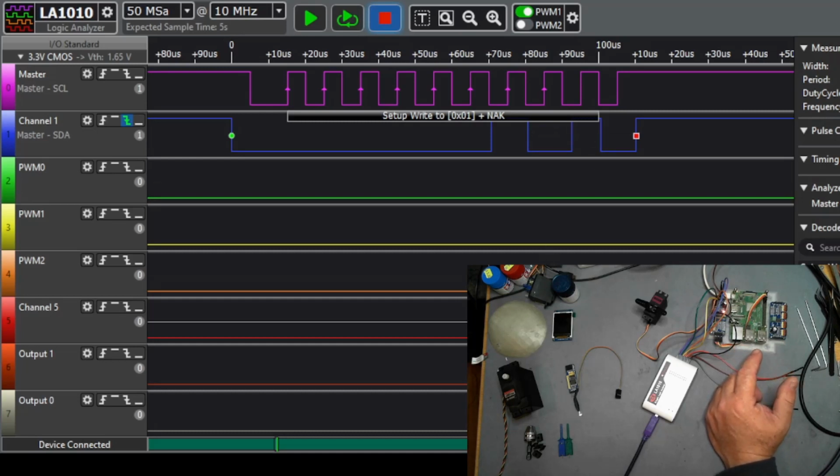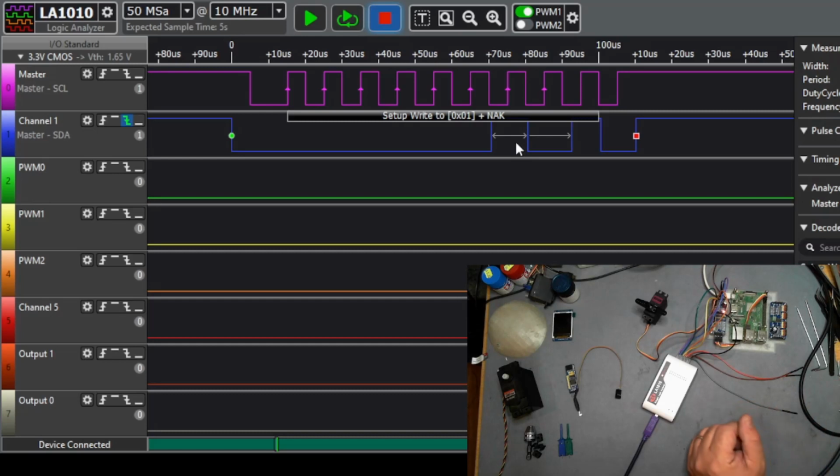So when the Raspberry Pi, MyRobotLab, does an I2C bus scan, which I've just done, it's actually just looking for an acknowledgement from the address, and it will actually send a read and a write to each individual address, all 124 or 126 addresses, looking for a response. Whenever a device responds, it just holds that acknowledge line down for that clock cycle. Alright, so let's get back to our web page.